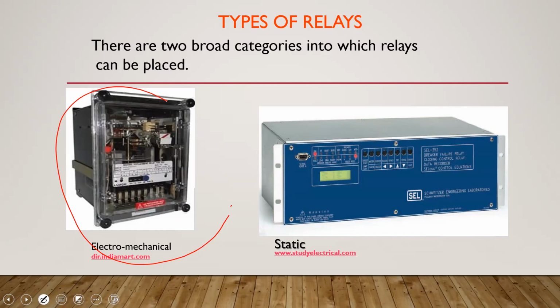Over here, this SCL relay will monitor all 3 phases. On top of that, you may be able to have more than one operation from it. So you may be able to get overcurrent as well as distance. So in other words, relay technology has resulted in the relay house not being as large as it used to be. I suppose the only drawback is that now you need air conditioning in your relay rooms.